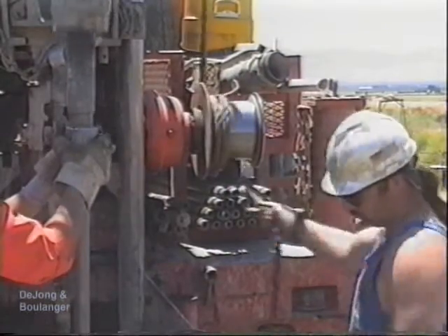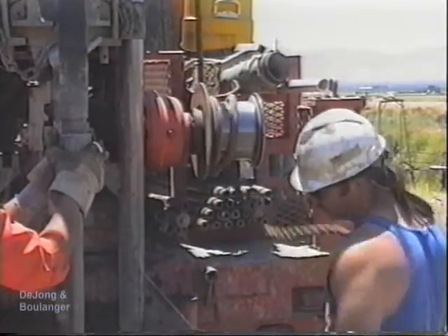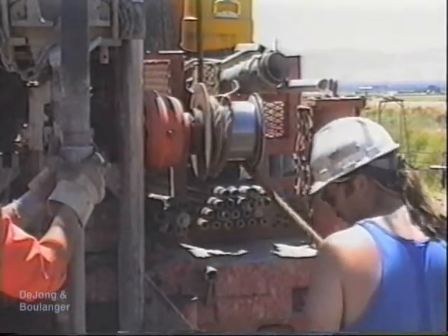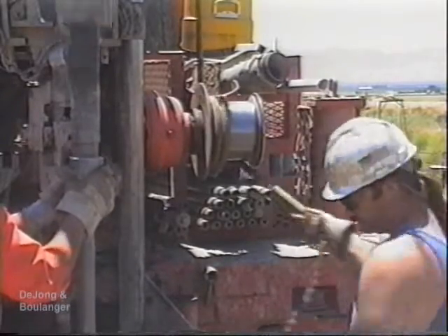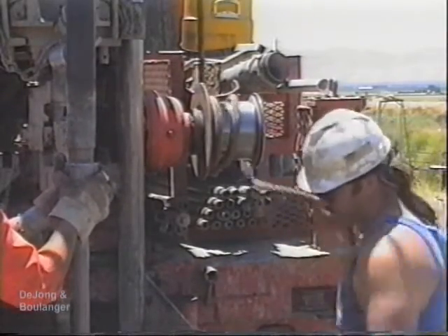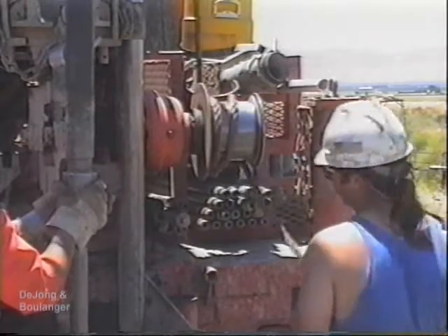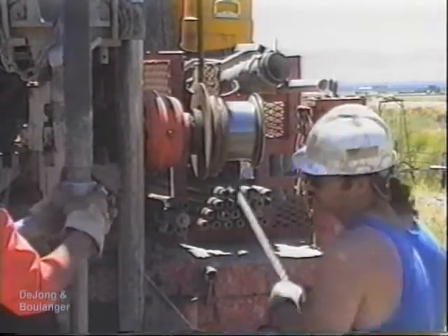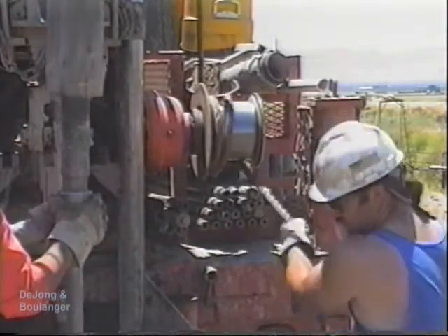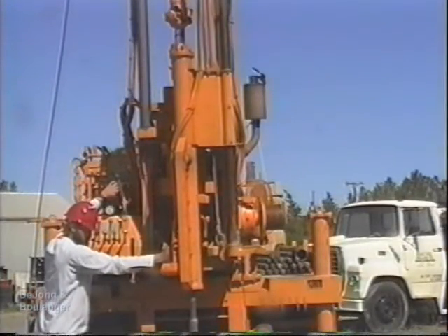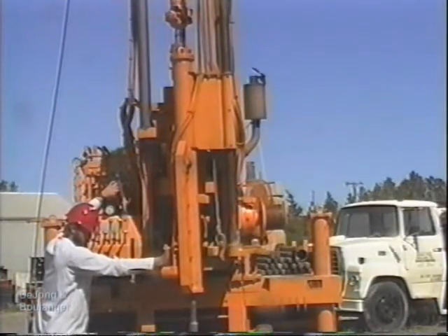The driller lifts the drop hammer by pulling on a rope that is looped around a rotating drum, or cathead. By pulling the rope, the operator uses the friction between the rope and the cathead to pull the hammer up. The hammer is dropped by releasing the rope, thus reducing friction between the rope and the cathead. The trip hammer performs the same function, only mechanically.